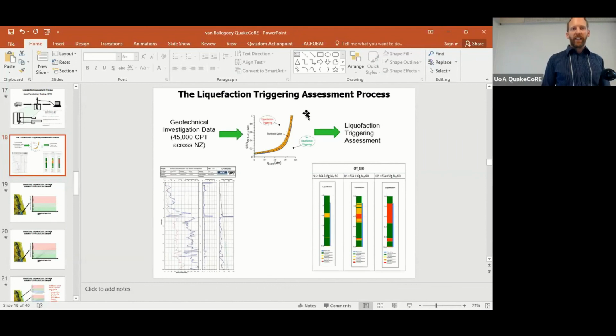The work shown to date is that with silts themselves, we're more coming across an issue of interlayered sand and silt layers where liquefaction is being predicted within the sand layers, leading to false positive prediction of liquefaction, compared to sites that are just pure silts. We don't have a lot of case histories of pure silts and whether or not they're liquefying, but it's one of the things that we're hoping to find and scrutinize.